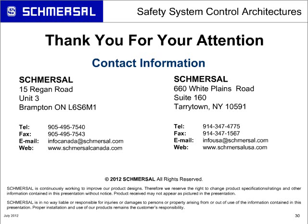The safety relay sees that the first circuit didn't clear, but the second circuit did. So when you close your door again, the first circuit has never cleared. The safety relay says, wait a minute, one circuit cleared, the other one didn't. Stop, I'm not turning anything on because I have a failure in my safety system somewhere. That's how it's detecting one channel versus two. So if you had that single failure, it does detect it.